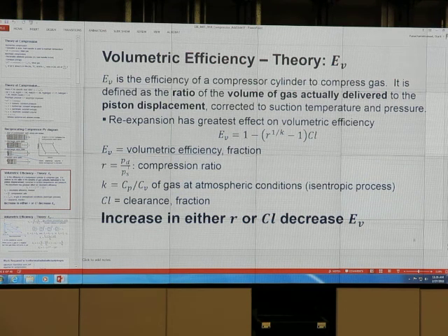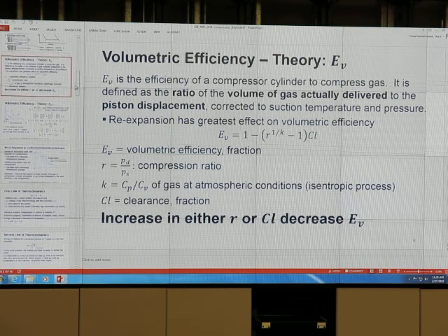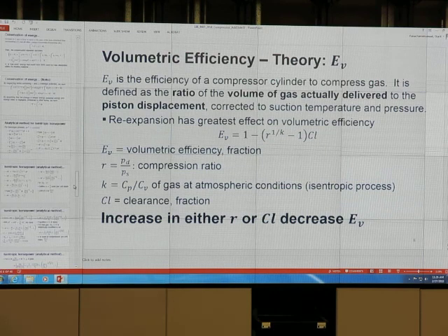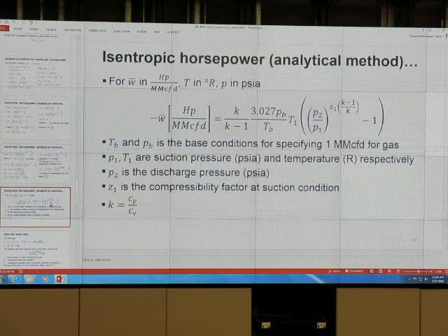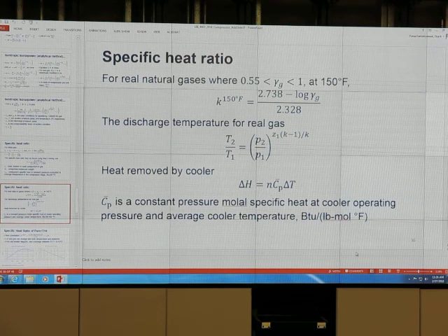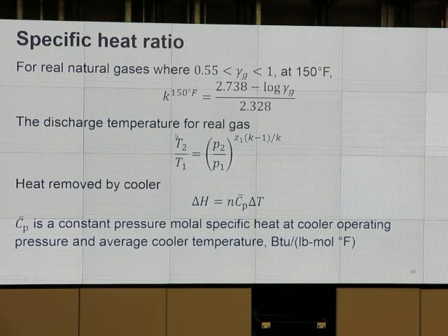For example, 0 psig, you have to convert to psia before doing any compression ratio calculation. You recall that? Good? Okay. So compression ratio is the ratio of discharge pressure over suction pressure in absolute units. Once we know that, we can predict what should be the output temperature.